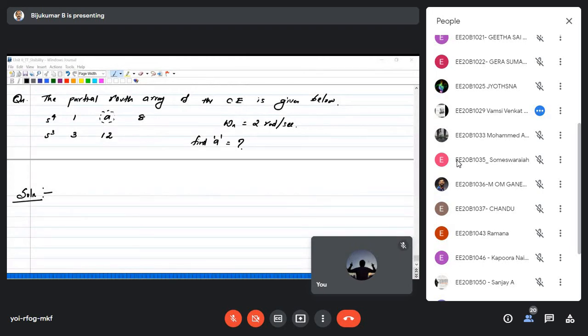And what is the observed location I'm asking? Can you tell from the question itself? Yes, sir. Natural frequency given as 2 radians per second, sir. So poles may be at plus 2j omega and minus 2j omega. No, plus or minus j omega n. Yes, sir. Plus or minus j2, sir. Yeah, that is correct. Otherwise, it is wrong. Okay, fine, good. Okay, you can mute your mic.